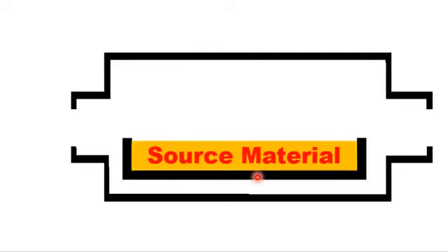So inside the precursor holder, the source material or precursor material is incorporated. Dear student, please note that closed space sublimation apparatus uses the source or precursor material in the form of solid powder or in the form of a chunk of material which we want to evaporate.